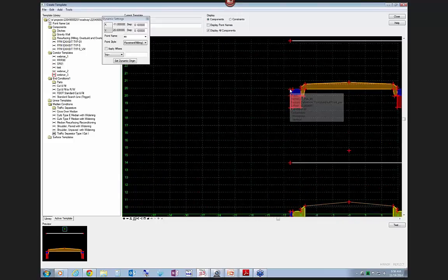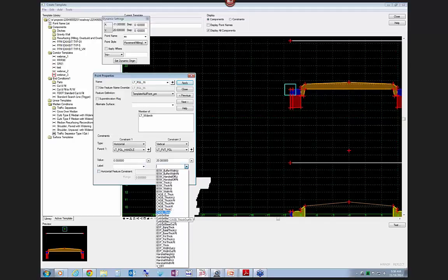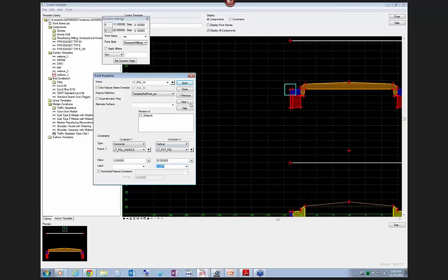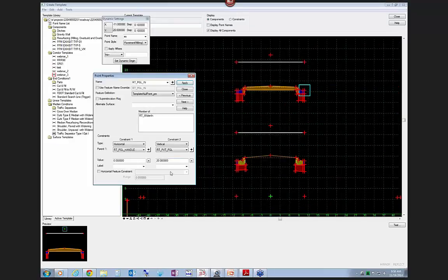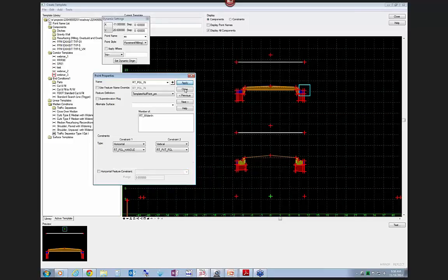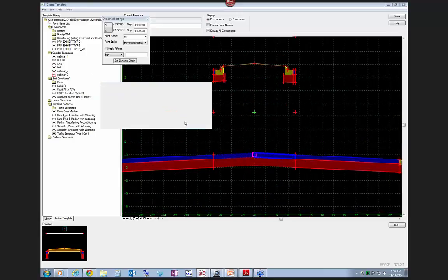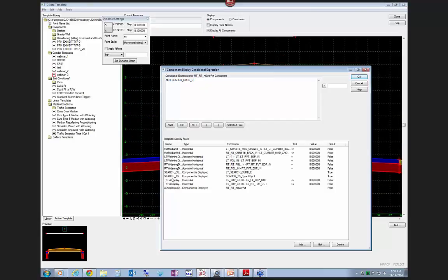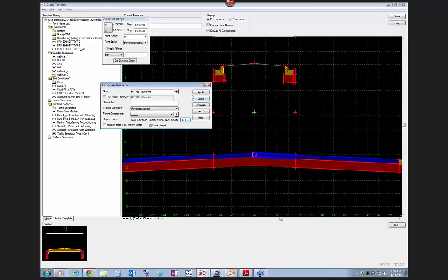Then I'm going to make sure that this label is set to V offset, because that's actually got to be placed down on the pavement in the corridor. Same thing over here. Choose apply. Then the last thing I have to do is make sure that this pavement doesn't draw if it also sees this traffic separator search line. So I'm just going to put in here "not when you see a traffic separator," and that's all there is to it.